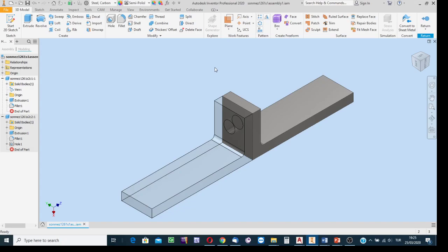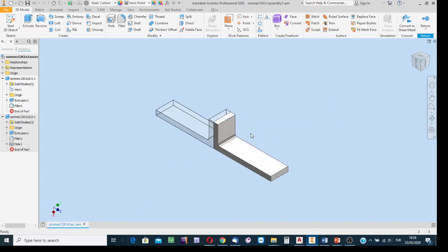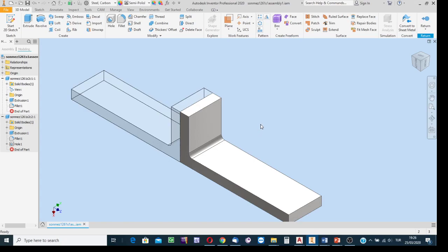Okay, yes. And then, do not apply the hole creation process. An easier method is that instead of trying to create the hole, recalling the location dimensions and the size and type values, just to have the hole coaxial and in the same size, use this technique: cutting, extrusion.